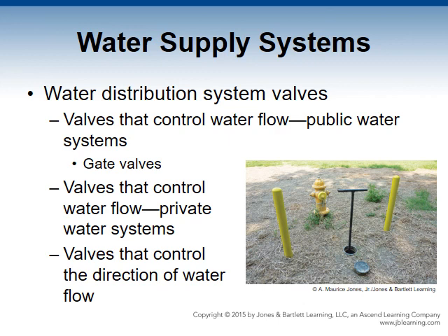Valves can open left or open right. A person must observe the effects on flowing water to determine if the valve is open or closed. By using the following general formula, it is possible to determine if the valve is fully open, partially open, or closed. The valve size in inches times 3 plus 2 will equal the number of turns to fully open or close the valve. Again, the valve size in inches times 3 plus 2 equals the number of turns to fully open or close the valve.